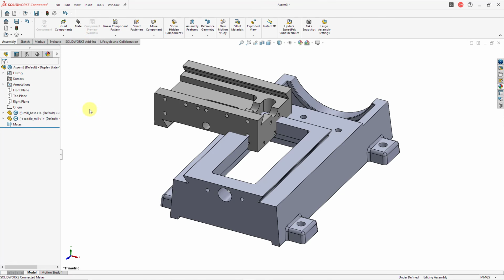And so again, this is one of the differences between Creo Parametric and SolidWorks. In Creo Parametric, when you bring in a component, you add the mates, or rather the constraints in Creo Parametric, in order to eliminate the degrees of freedom. In SolidWorks, you can throw in all your components and then add mates, and you can add mates in any different order. It doesn't have to be dependent on parent-child relationships and stuff like that. But anyhow, I've got this first component located in the model.